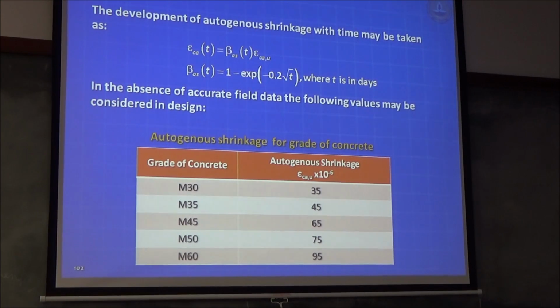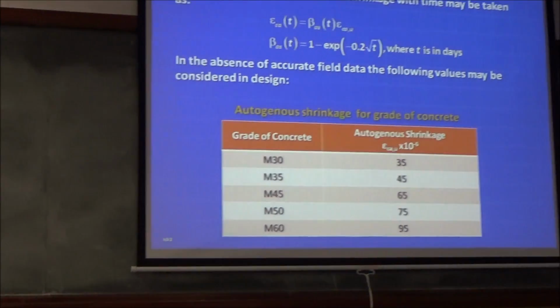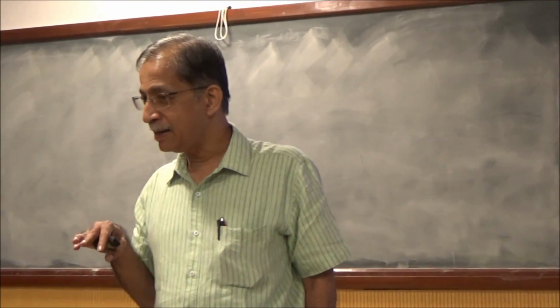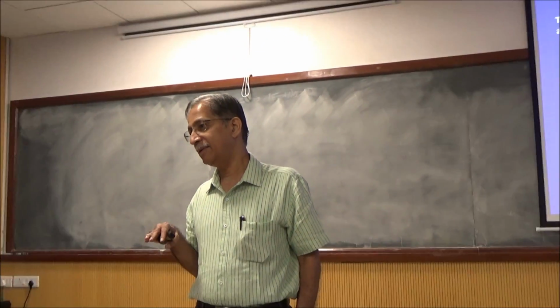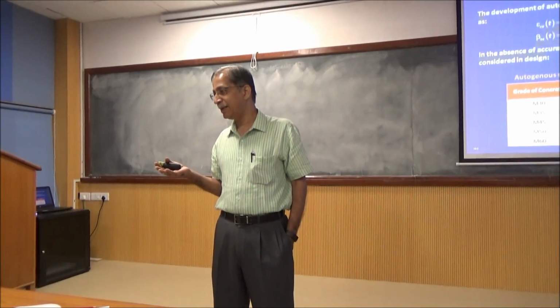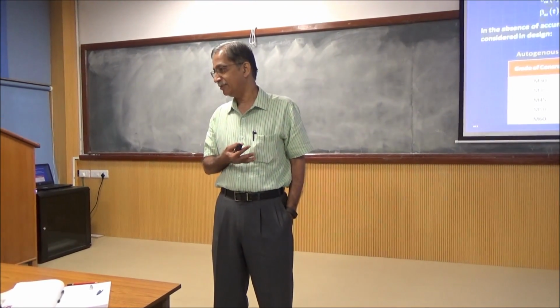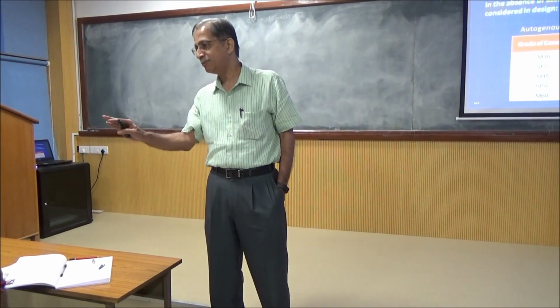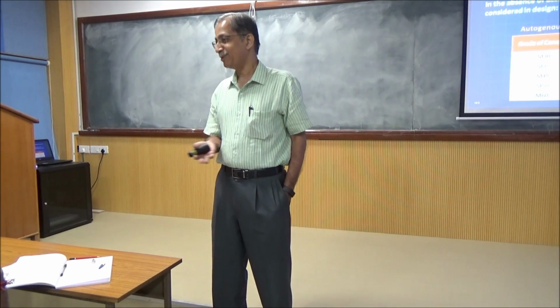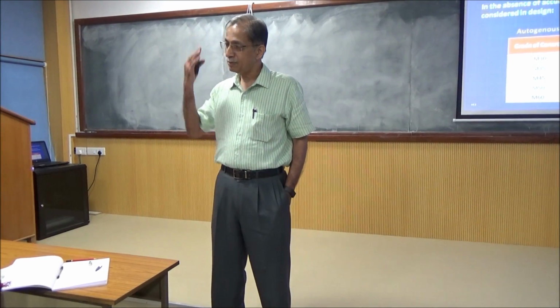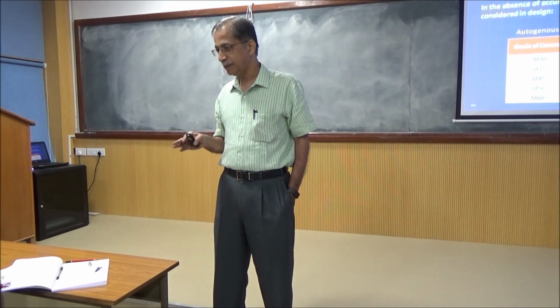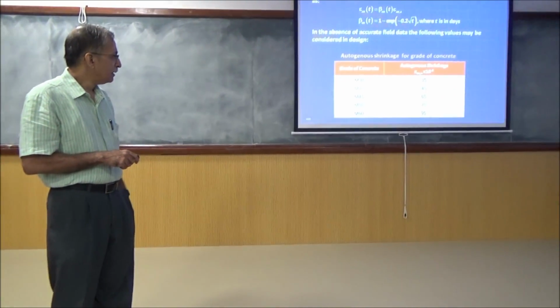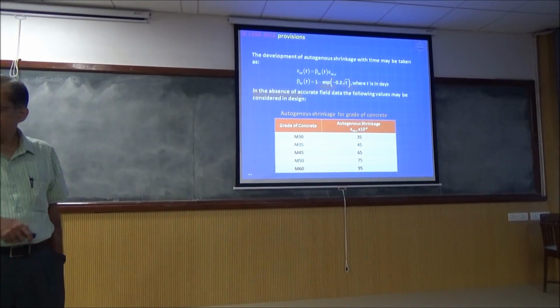It actually is not telling the whole truth. If you had to build a structure in, say, Jaisalmer in Rajasthan, will you take a higher value or lower value? If you had to do it in a place like Kerala, where it rains all the time, will you take a lower value or higher? Well, don't take lower, at least 0.003. The code says that, but it can go three to four times that. So you have to understand it. But compared to that, this is very, very low.